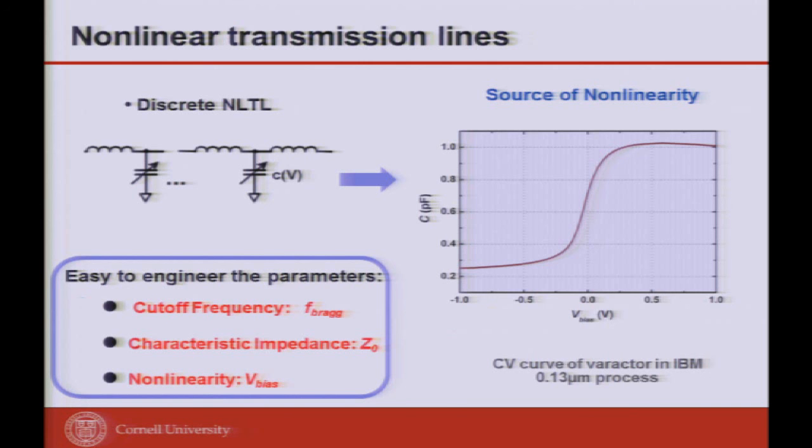The second is a broadband impedance. If you plot the nonlinear transmission line impedance, I'll show you immediately, it's a broadband condition. I can find a relatively broadband region where I do not need any matching network. You can see the antenna is a transmission line, right? Think about it, the simplest antenna is bending your transmission line by 90 degrees, so that the transmission line can work with broadband matching. Broadband matching is a very important thing for harmonic generation, especially for the locating. I'll show why this is important.